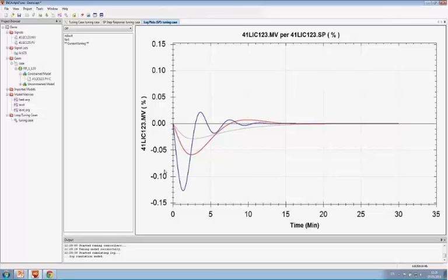This picture is normally checked if you are tuning a level, and it will make sure that if you have a response to a load, as I'm showing now, how will the controller perform. You see that the fast controller has a lot of oscillation still in there. Our robust controller also has an oscillation or 2, and our, let's say, soft controller has no oscillation.